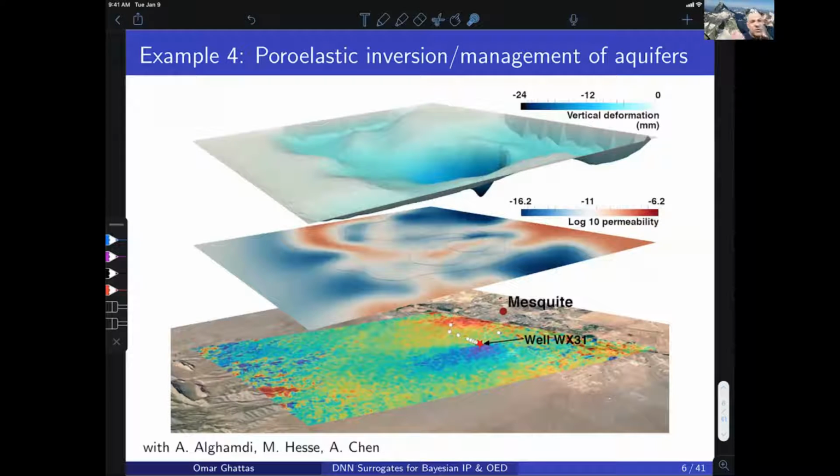It turns out, when we solve the inverse problem, which is a coupled poroelasticity equation, coupling subsurface flow with elastic deformation, what we end up inferring, because of the surface signature, is that there's a region of higher permeability there, which leads to large displacements in that region. We have solved this in the Bayesian context.